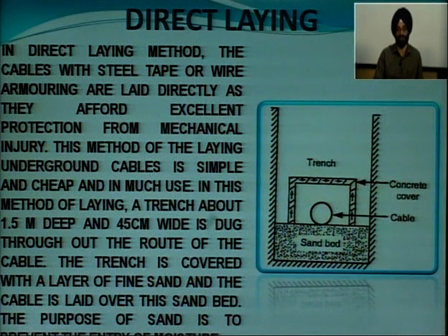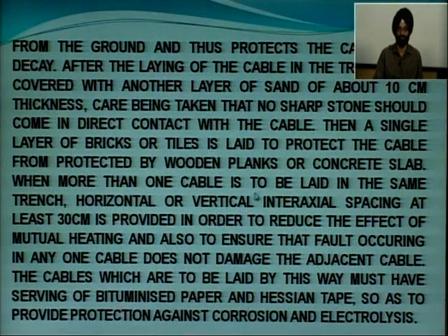The cable cannot be ruptured. So this is the method from the ground, and thus protect the cable from decay. After laying of the cable in the trench, it is covered with another layer of sand of about 10 centimeter thickness, care being taken that no sharp stone should come in direct contact with the cable.